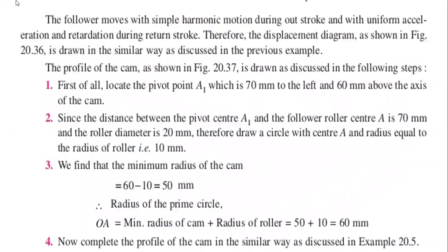Then we have to take the following procedure. Because the follower moves with simple harmonic motion during the outstroke and uniform acceleration and retardation during the return stroke, the displacement diagram is drawn in the similar way we have discussed.